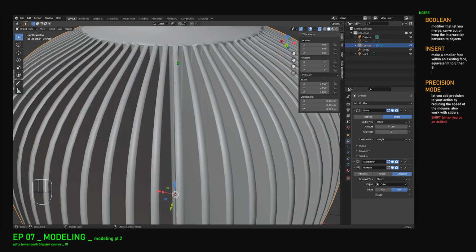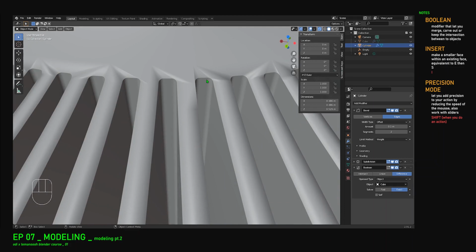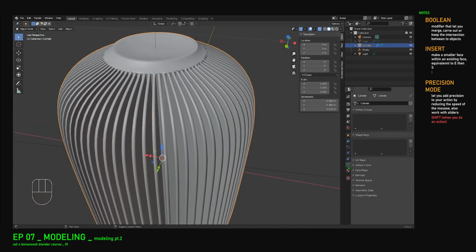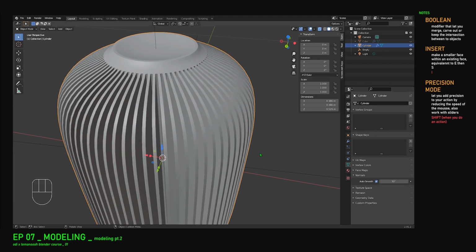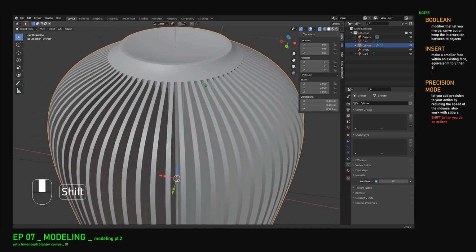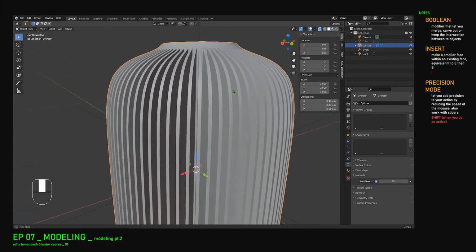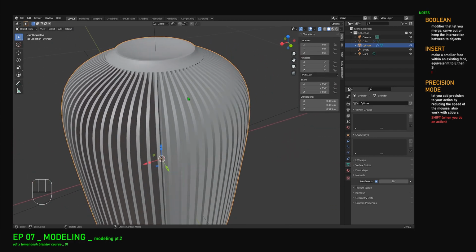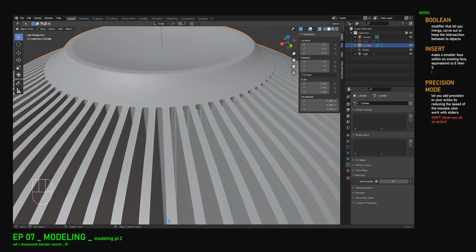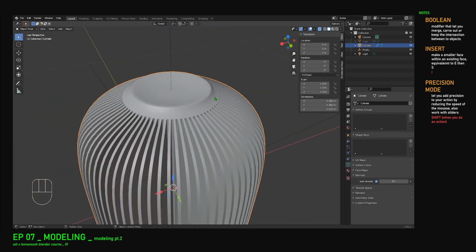The thing though is that we have some problems there in the normals. You can fix that by going here in auto smooth. Basically the auto smooth will not try to smooth everything out with the shade smooth settings we did earlier, but it will try to see at which angle it has to be considered as sharp and which angle it should be considered as smooth.